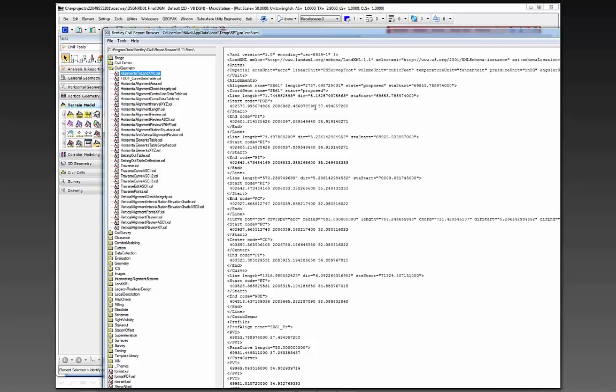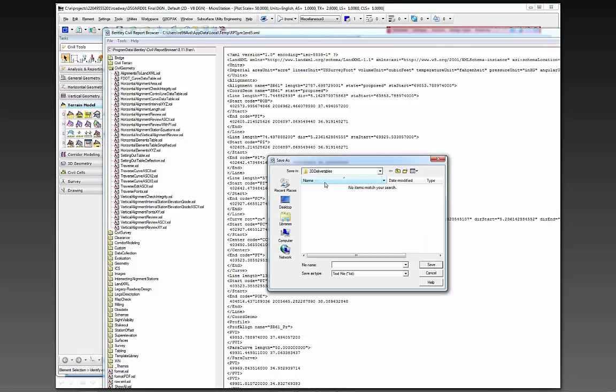After you create these LandXML files, I'm going to show you that we've also provided a viewer in our workspace that you can use to validate the LandXML files, so that they're in a common LandXML format that most of these machines will be able to read in. When you do that, once you have formatted this report, you'll do File, Save As. Then you're going to save this file to the name in the CAD manual.